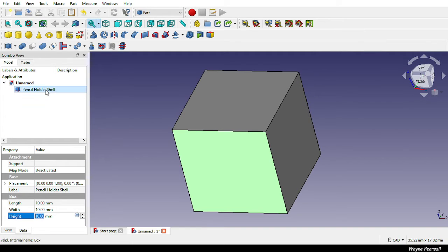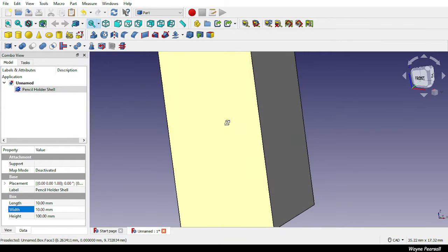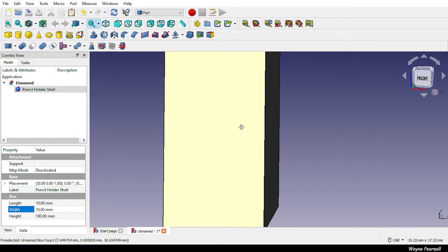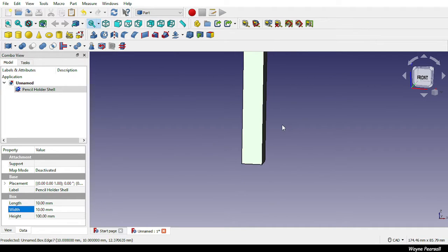So we've selected the shell part that we've just renamed, 10 centimeters. And here you can actually type in 10 centimeters and it'll convert it to millimeters, or type it in, and it's 10 centimeters tall now. Now if you think about how tall that is, a little pencil case ruler is 15 centimeters, so it'd be 2/3 in.